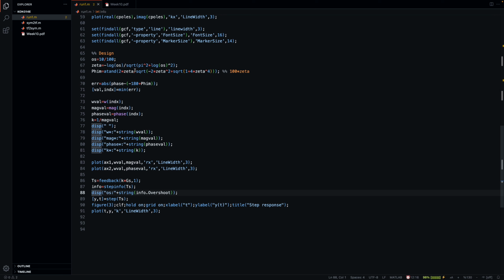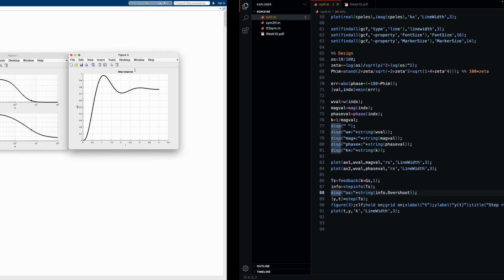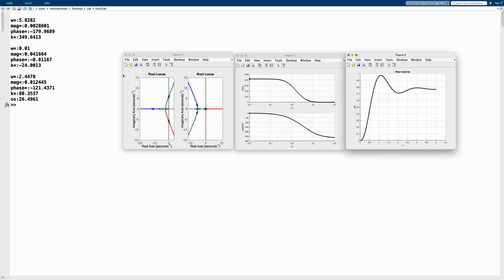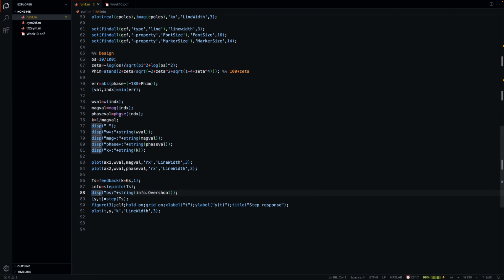That would mean that we are talking about a pole pair, but we have a third order system here. Therefore, we have 3 poles, and the overshoot to zeta to phi m mapping might not be quite correct because it's about a second order system. Here again, we see that the second order system is quite important, and most of the formulas are again obtained for second order systems.